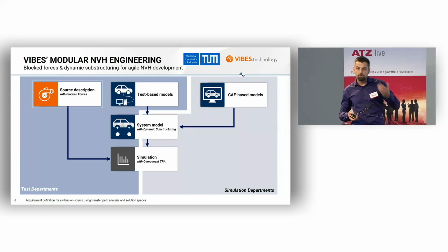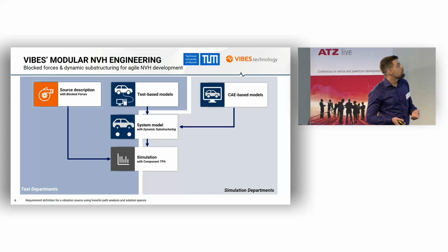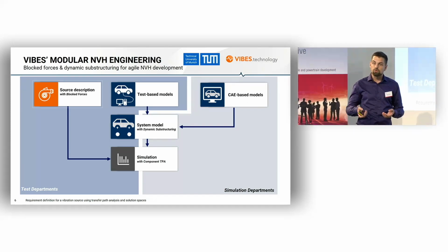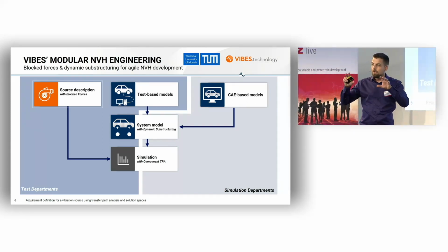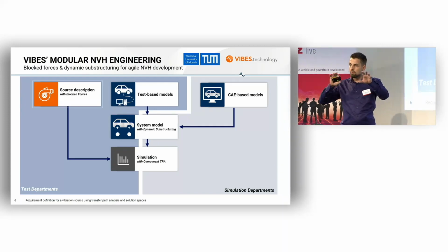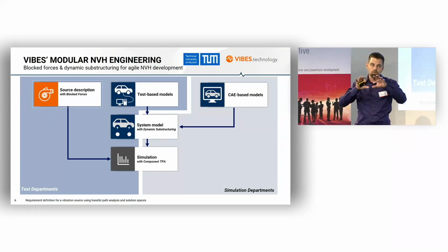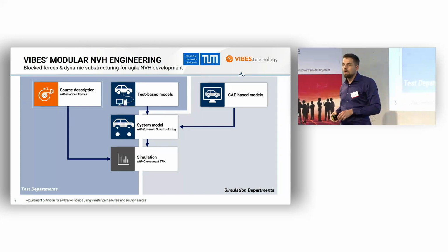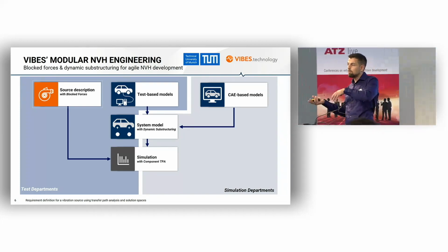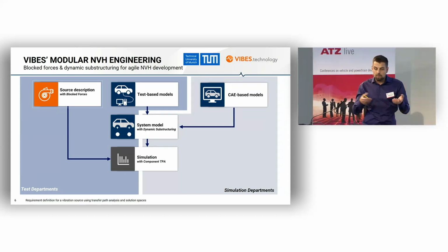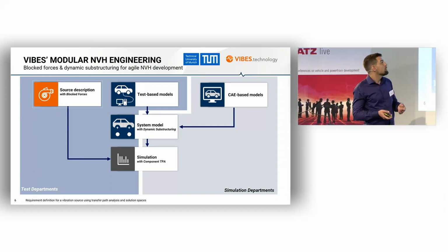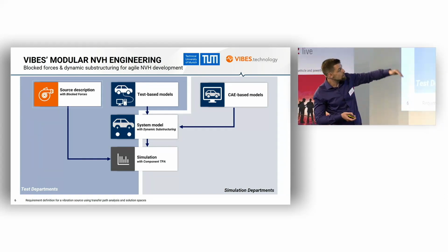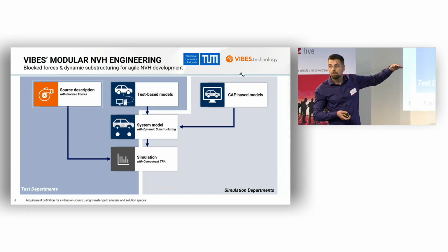We're trying to make software to make this accessible to industry, because it's actually quite nice to be able to, like Lego blocks, assemble your structures and choose the easiest and most accurate approach for each of your substructures in the transfer path. So either an experimental model, a simulation model, sometimes for rubber bushings just analytical models, and then simulate the transfer path of the whole assembly.